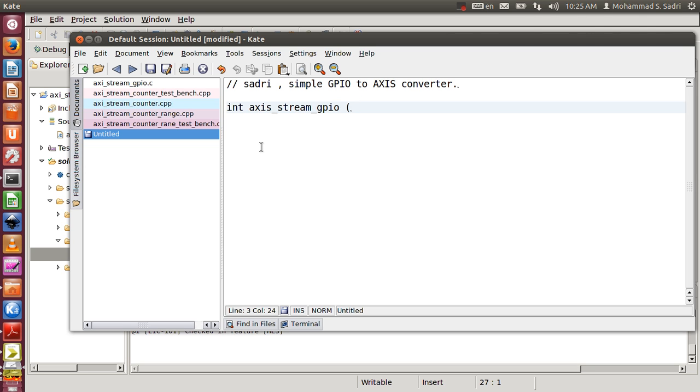and here I put the GPIO which is entering my module, and here I want to use the data structures provided by Vivado. So if I recall correctly, API int, and for now I want an input port of 1 bit width.